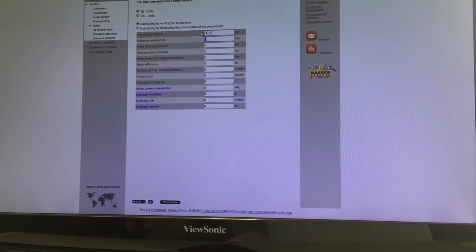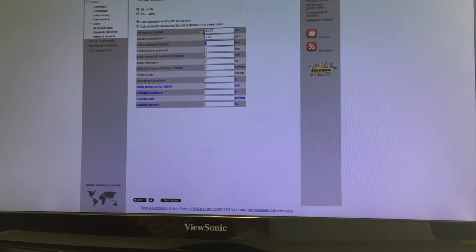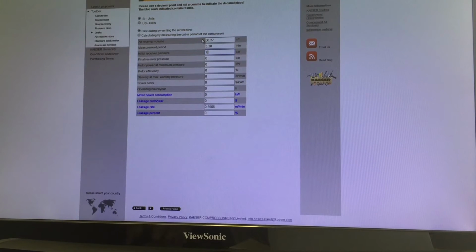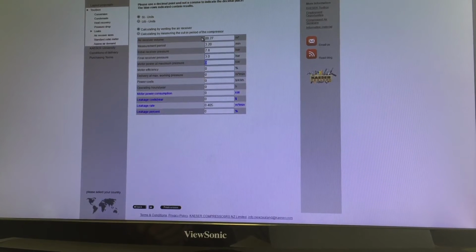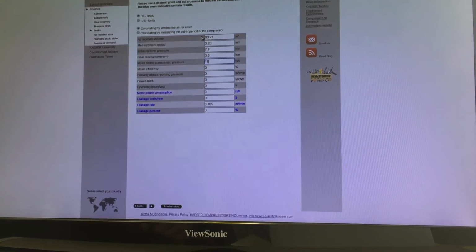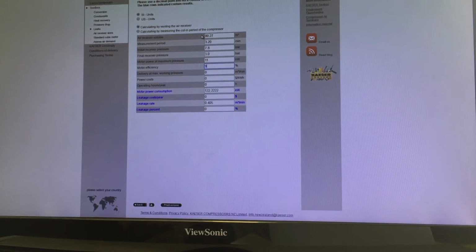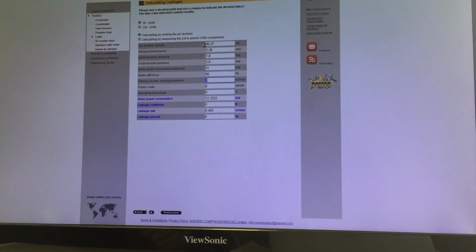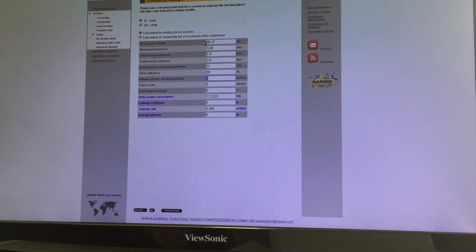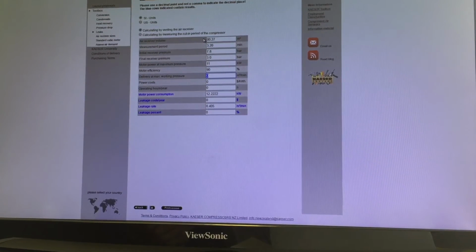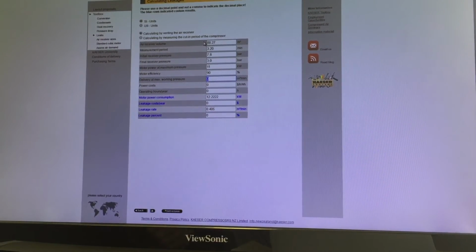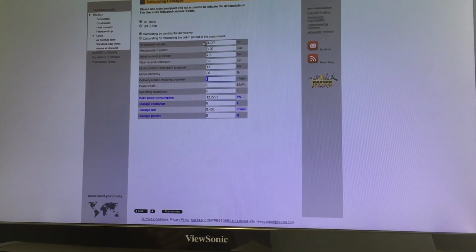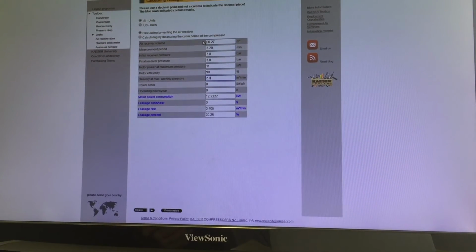So we'll use the 3 minutes 20 for a bad air leak. Initial receiver pressure was 7.8 bar. Final receiver pressure was 3.0 bar. Our motor power was the 11 kilowatts. Our motor efficiency, if you use a default 90%, that's a fairly average efficiency. Delivery at maximum working pressure, again if you ring your service provider or ring Compressed Air Controls with the make and model, we'll better tell you that. We were using a Kaiser SK22 air centre, so it has a volume of 2.0 cubic metres per minute.